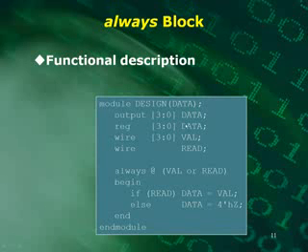So here we have an output, 4 bits wide, and we have a wire that we're using in this module called val, and another wire called read. And here we have an always block, so anytime that val or read change, it goes through this always block. And then data is based upon these two inputs here, val and read.